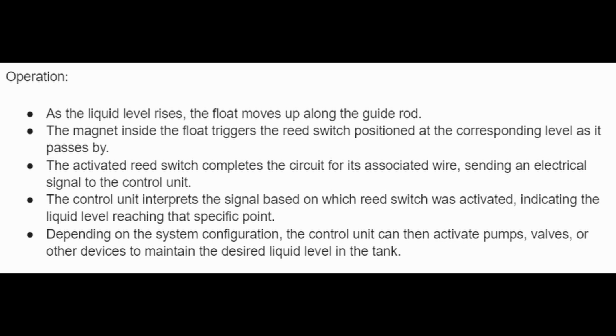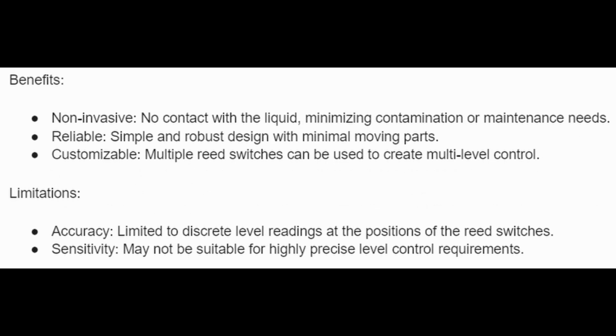Depending on the system configuration, the control unit can then activate pumps, valves, or other devices to maintain the desired liquid level in the tank. Benefits. It's non-invasive, no contact with the liquid, minimizing contamination or maintenance needs. Reliable, simple and robust design with minimal moving parts. Customizable, multiple reed switches can be used to create multi-level control.